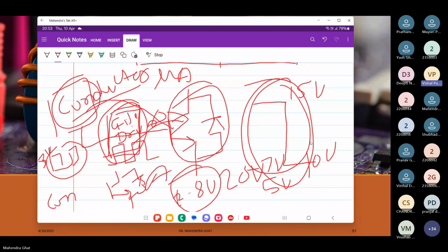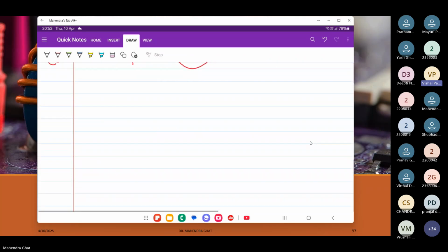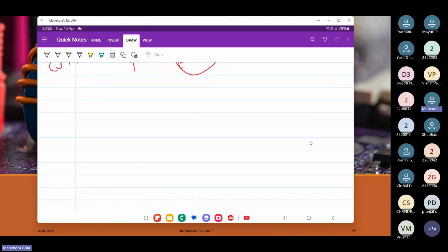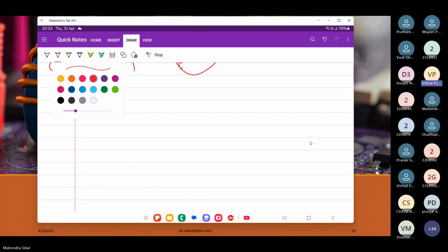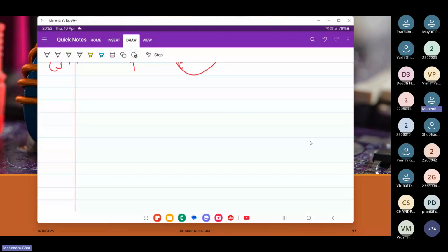For gate driver, we need to check the data sheet for the gate current of that switch. Nowadays, gate driver ICs are available. Earlier, it was done on PCB with optocouplers. We had to use the transistor and optocoupler for isolation, and to boost the voltage level. Transistors and everything were used in previous days. But now all are coming with gate driver ICs, which will give whatever requirements are there.